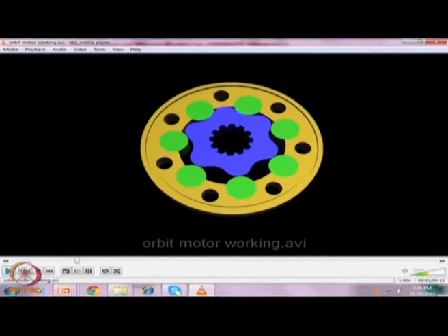So this is the star and this is the ring. This is the modified epitrochoid that we have learned, and this is basically the envelope. This modification is nothing but the constant-difference inward shift of the original epitrochoid generated, for which the envelope actually goes through this center point. If we modify this envelope, we find this contact portion becomes a circular arc.